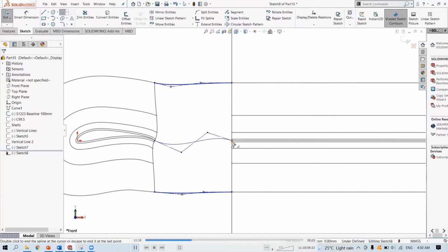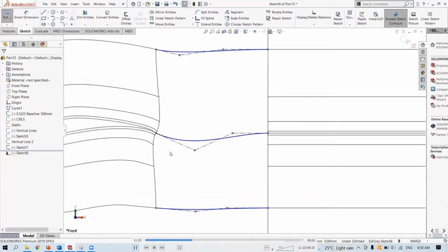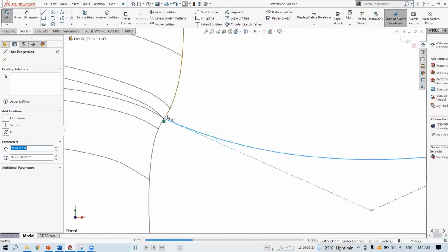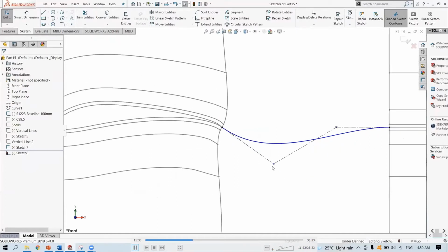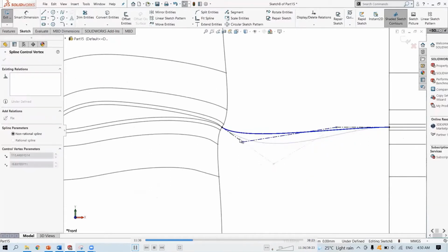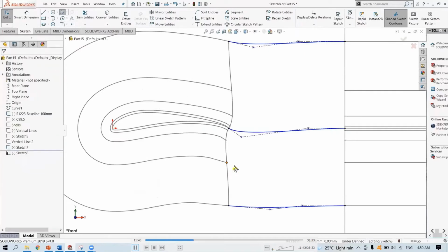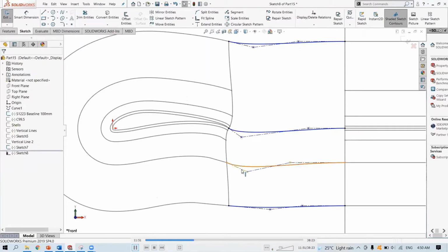Okay, starting off from the trailing edge, horizontal, and then this one can be perpendicular to the guide curve. It's the same thing because we have designed the estimated line just now near the trailing edge, right? So just continue doing it for the third shell. Horizontal, tangent.